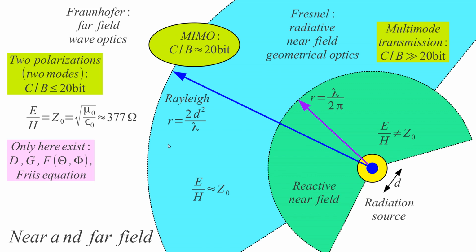The in-between region, this is where we are trying to make use of the very high spectral efficiencies, like massive MIMO, like communications in the millimeter wave range. With small distance and relatively small antennas, d squared, but much smaller lambda, we can further increment this region.